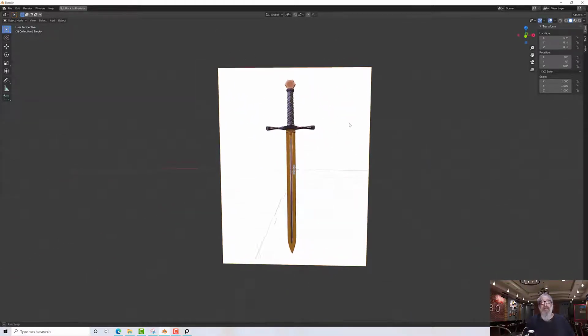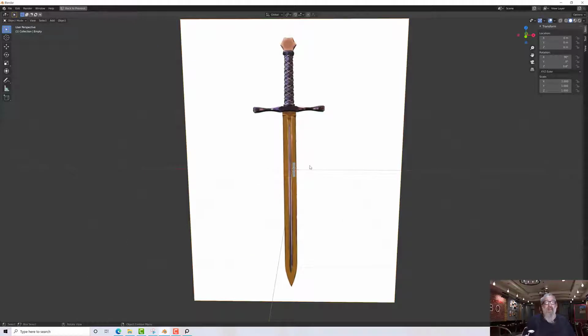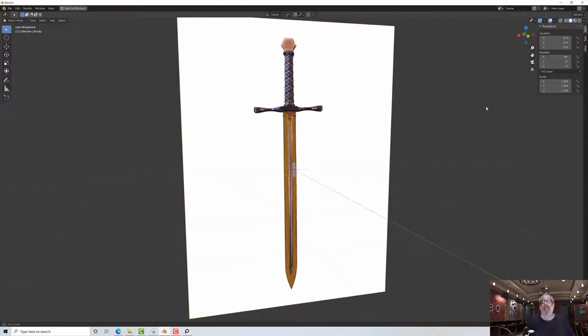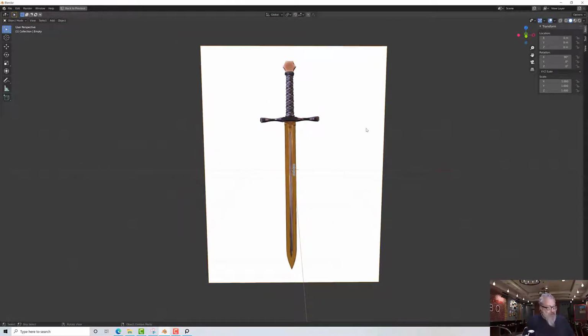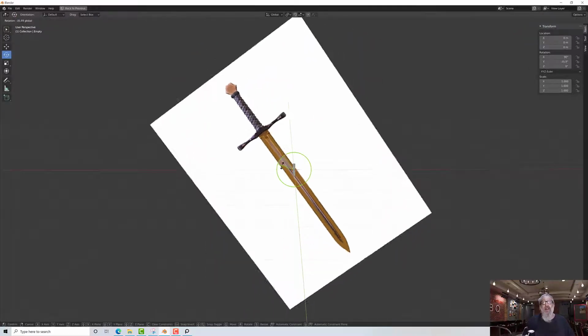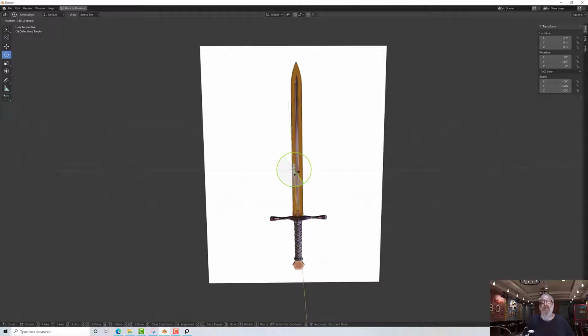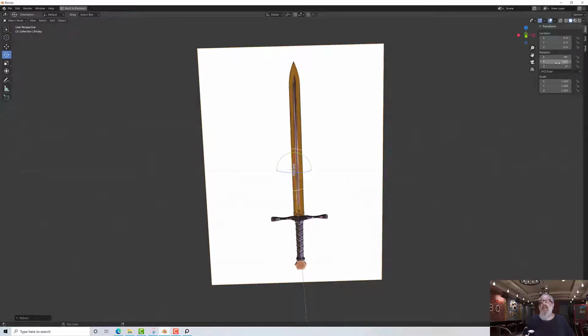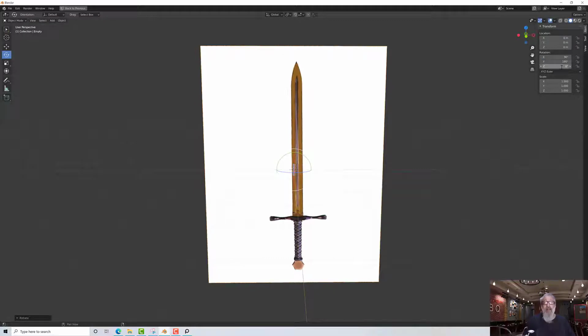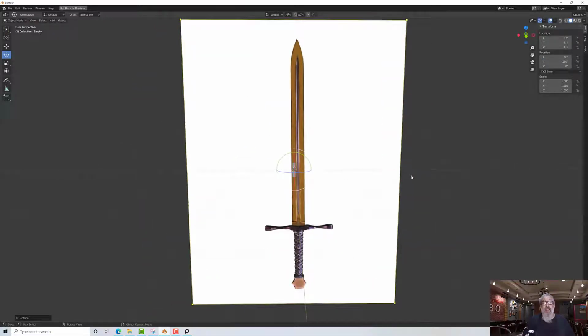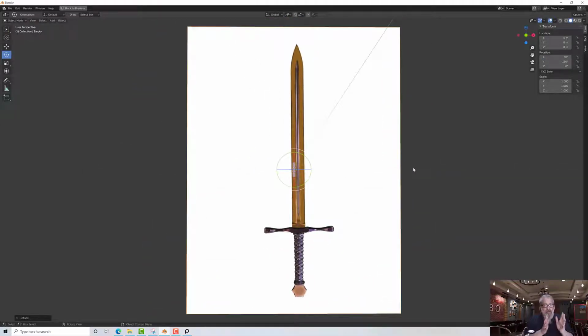Now it's straight. And actually I want to model this in the other direction. I've got a little rotation on there as well. So let's rotate it. If I press the R key, I can start to rotate it, and you'll see my properties start to update over here. So I could just type it in here, 180. There we go. Okay, so now I've got my image in.